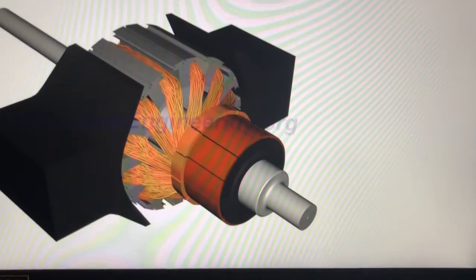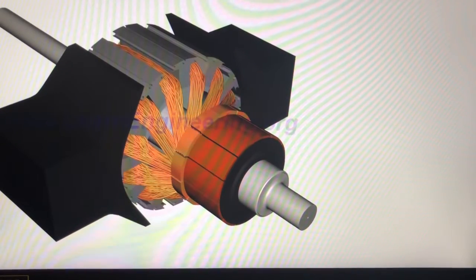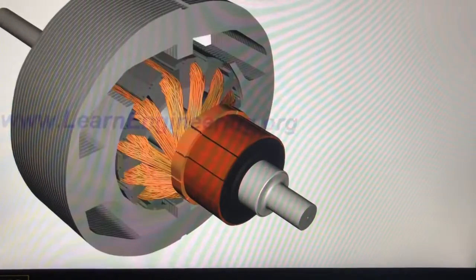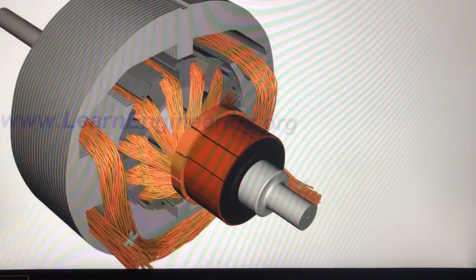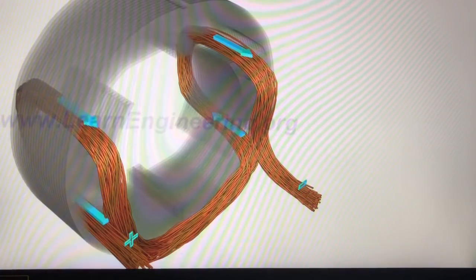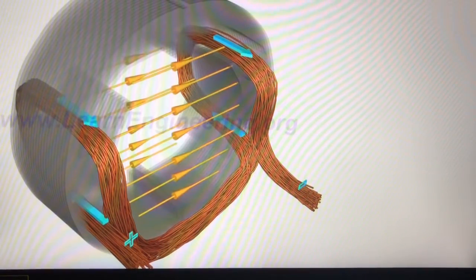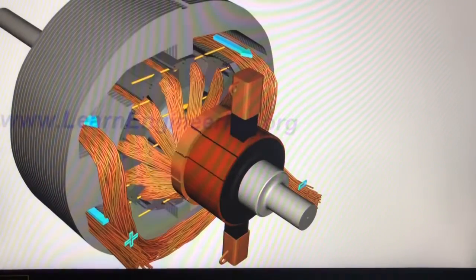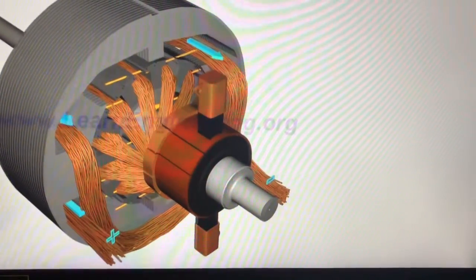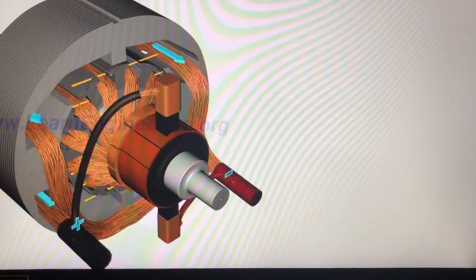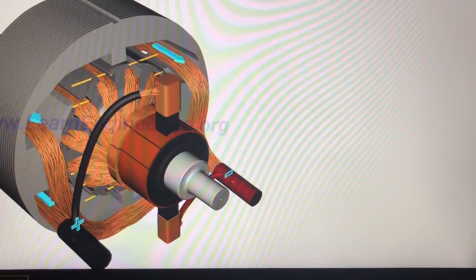A permanent magnet stator pole is used only for very small DC motors. Most often, an electromagnet is used. The field coil of the electromagnet is powered from the same DC source. The field coils can be connected to the rotor winding in two different ways: parallel or series.